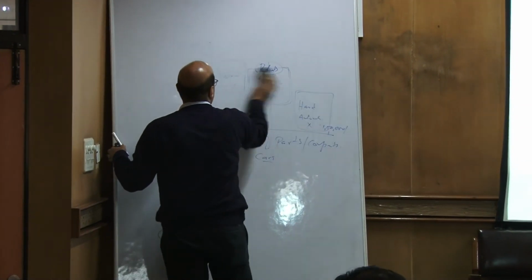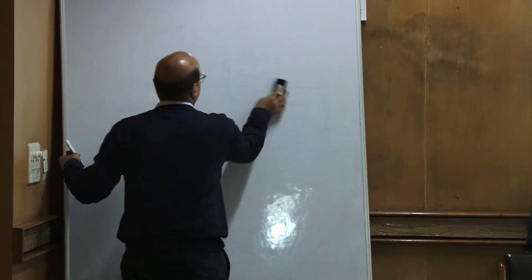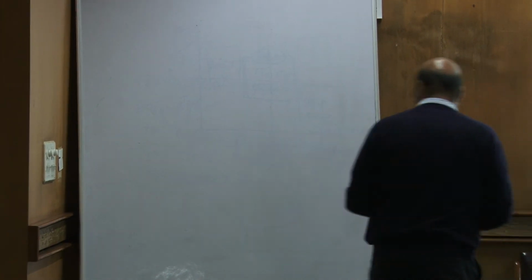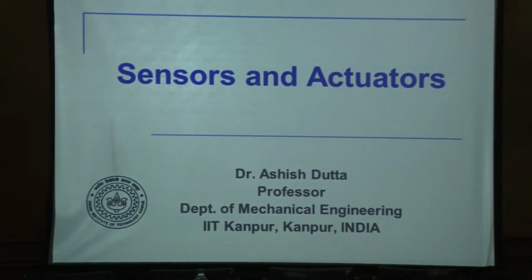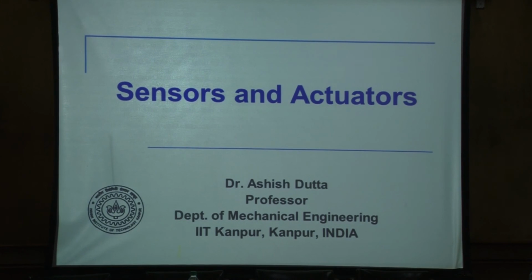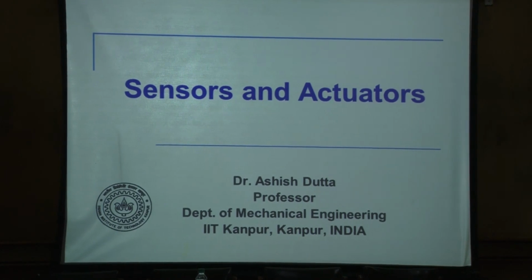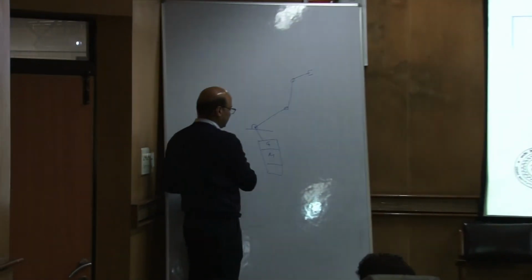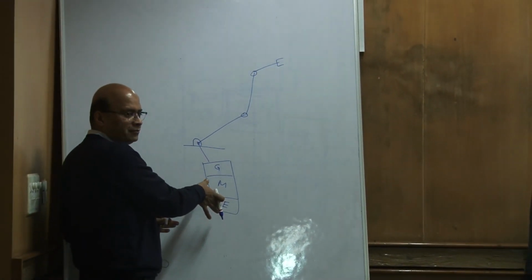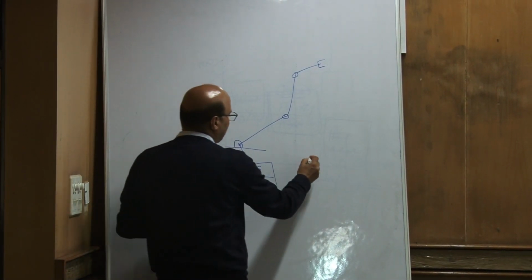So till now we were talking about kinematics, a little bit of transformations and all that. But if you have to come to the labs and make robots by yourself, then we'll have to talk about the controllers. The robots are actuated as follows: we have a joint, and each of these joints is connected with a motor, which is an actuator. There is a gear in front to increase the gear ratio, and there is a position sensor like an encoder at the back. Each of these comes as one compact unit, and this is called independent joint control.